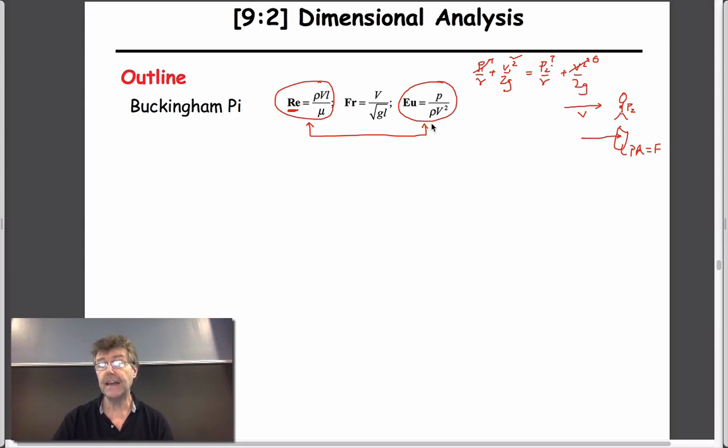And you see some interesting scaling things here, and that is that you could surmise from this that the force is proportional to the velocity squared. And so that means that if you double the velocity, you quadruple the force that's applied to it. And so it's not a linear relationship. You can't necessarily define that from this, but we'll find out that that really is the case. So if you're free falling through air, if you're going at 1 meter a second versus going at 2 meters a second, the forces applied onto you as drag will be quadruple, not double, as a function of that. And so those are the two principal ones.